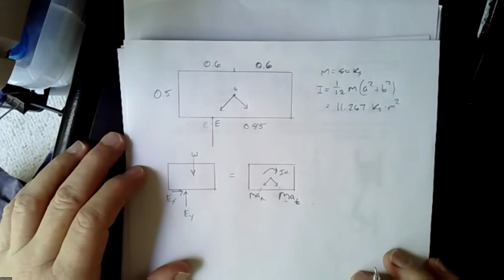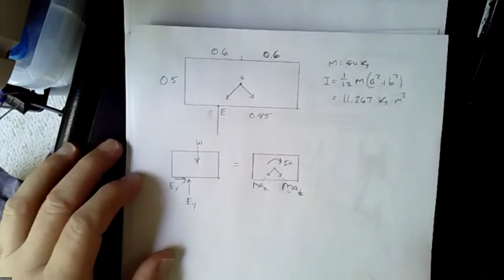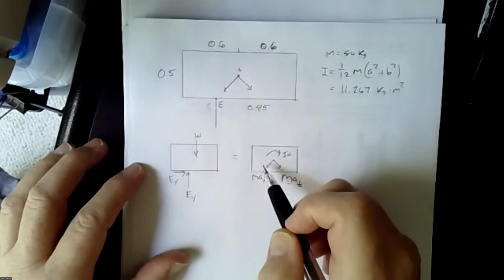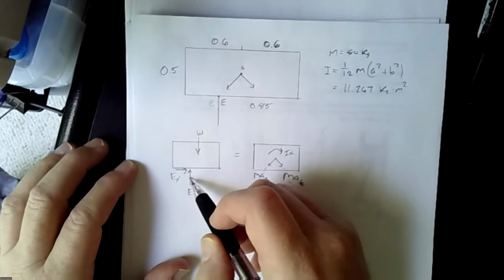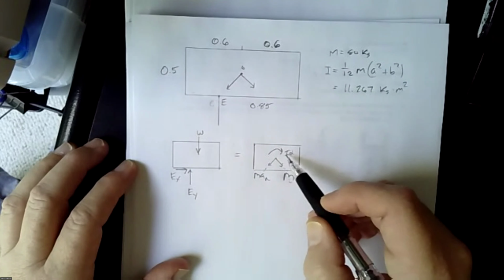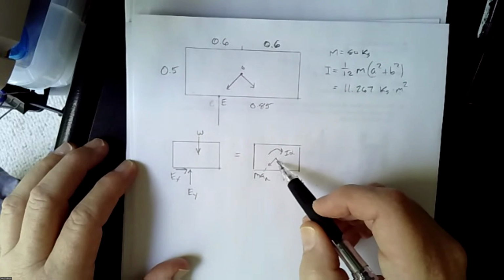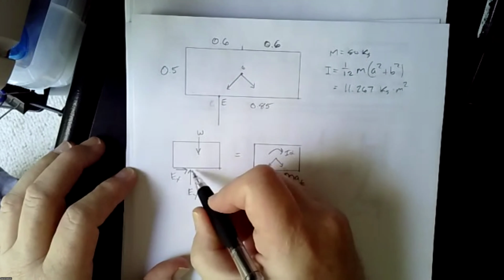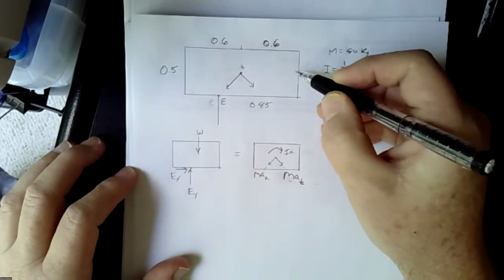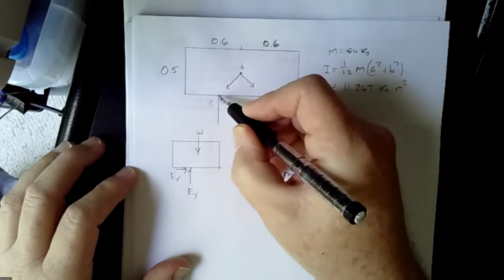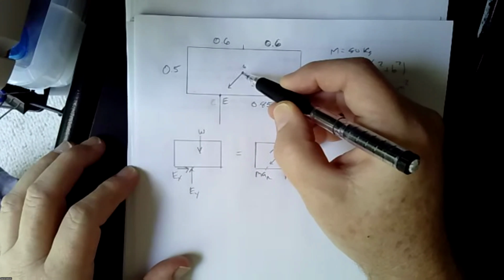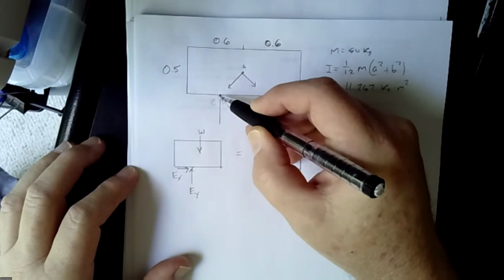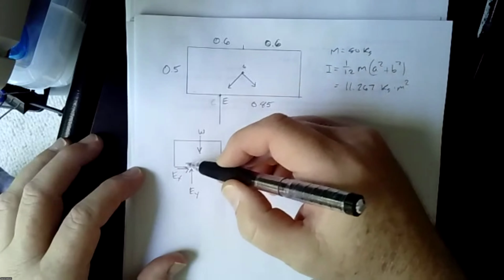All right. Now, you notice that I've drawn my free body diagram down here. So just like before, you have our weight and this our reaction E. And then here we have I alpha and then the acceleration of the center of gravity. Now, even though it's constrained, meaning that when we release it, it's going to pivot around E, we still look at the acceleration of G. We don't look at the acceleration of E, because obviously E doesn't go anywhere, it's just a point.